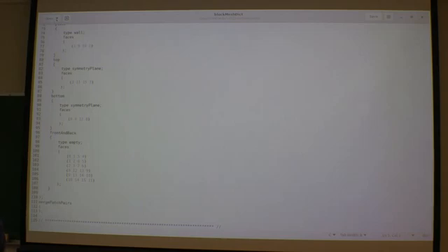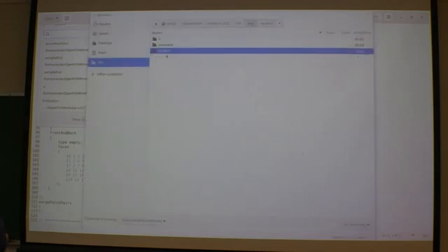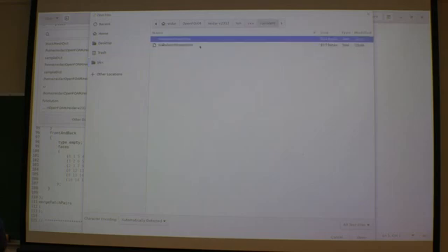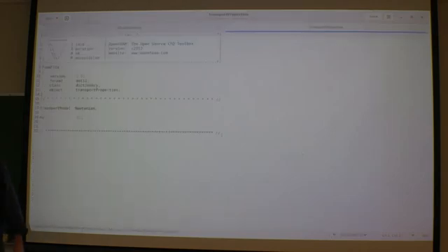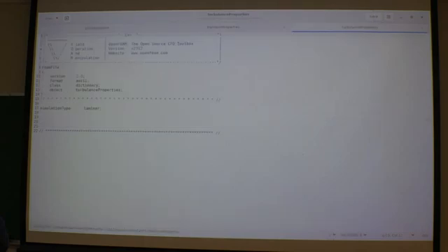Let's have a look at the rest of the setup here. I had chosen a laminar case, and let's start with a Reynolds number of say 10. My plate is 1 meter, viscosity here is 0.1, and I'm sending in 1 meter per second. Now let's also have a look at the turbulence. Laminar, very easy.